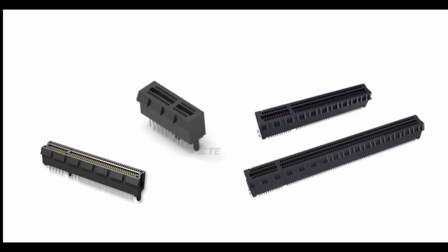Basically, the more lanes you've got, the more bandwidth you've got. The more bandwidth you've got, the more data you can transfer at the same time. So the one at the top left only has one PCIe lane on it. That'd be useful for a modem or a printer or a joystick that doesn't input or output much data.